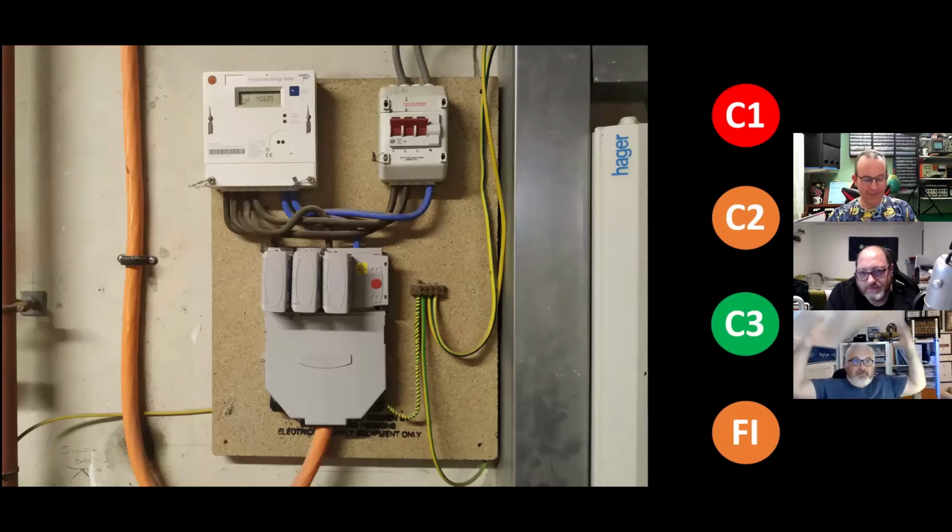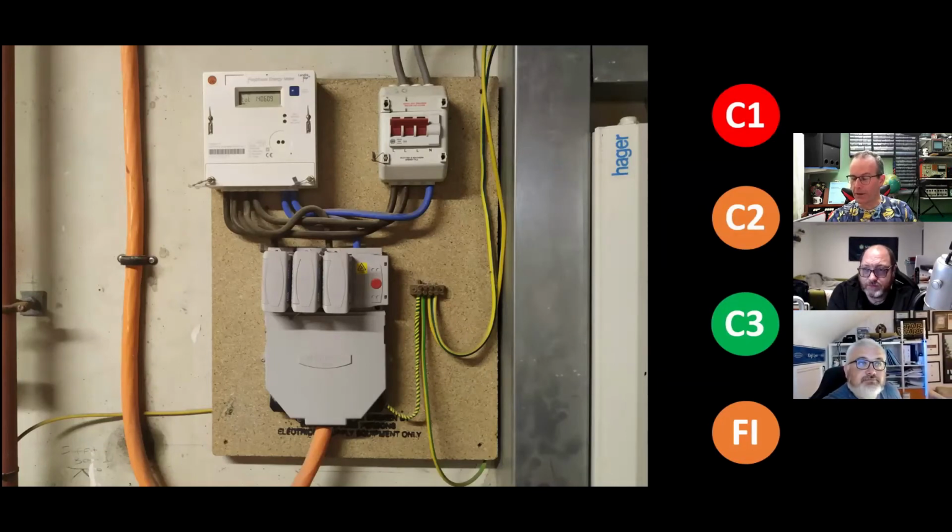Mind blown. And the phase converter in the lift is very interesting because trying to run a 3-phase lift, and it's about a 16 or 17 kilowatt lift, running off of a phase converter. So you can just imagine the starting current off of the single phase when that thing switches in. I think the peak current is something about 120 amps when the lift actually starts. And this is on a 100 amp supply. So yes, it's a complete and utter disaster.